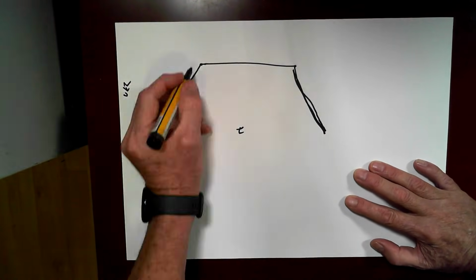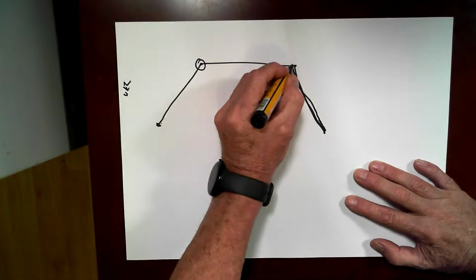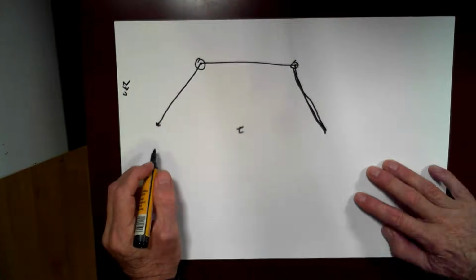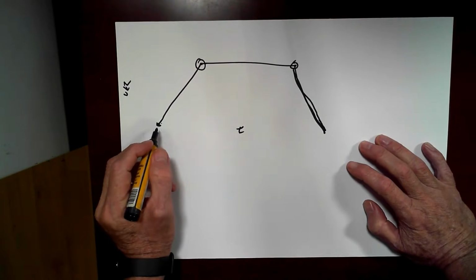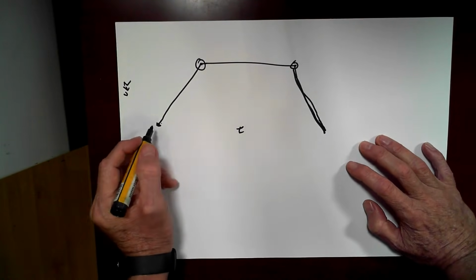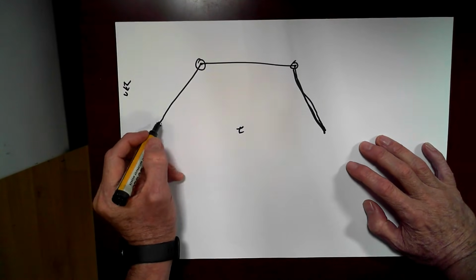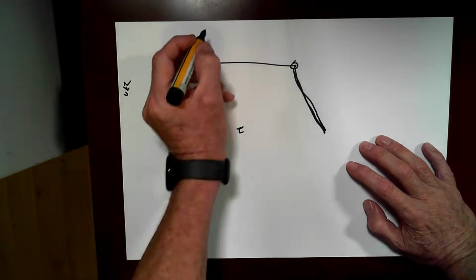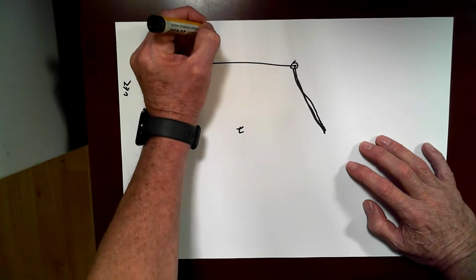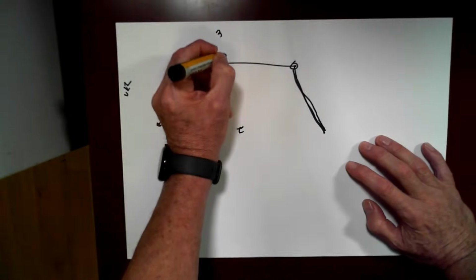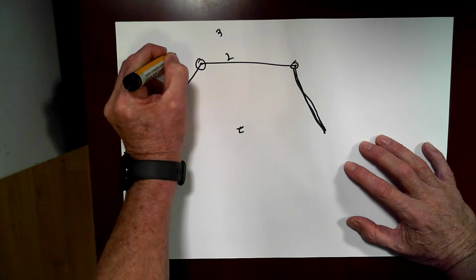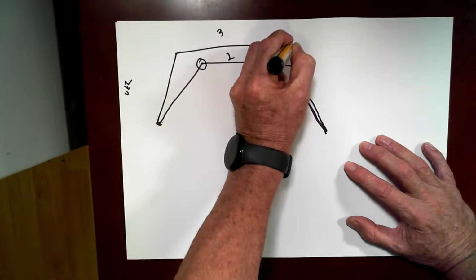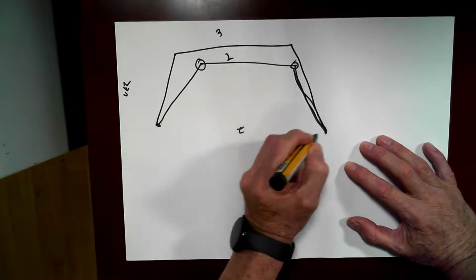So these are the points that cause jerk. And this jerk can limit your tuning ability on the maximum velocity that you run. You might want to run this at a faster speed, so you might want to cut at 3 meters a minute instead of 2 meters a minute, and you might want to accelerate a lot faster and then come across here and come down a lot faster.